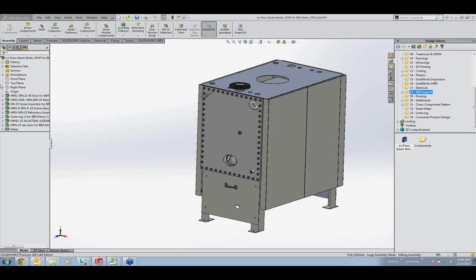Now, this is called the distance linkage. You can see that this component no longer is able to rotate around the path. It will follow the path, and the path will go through the centers of those 2 arcs.